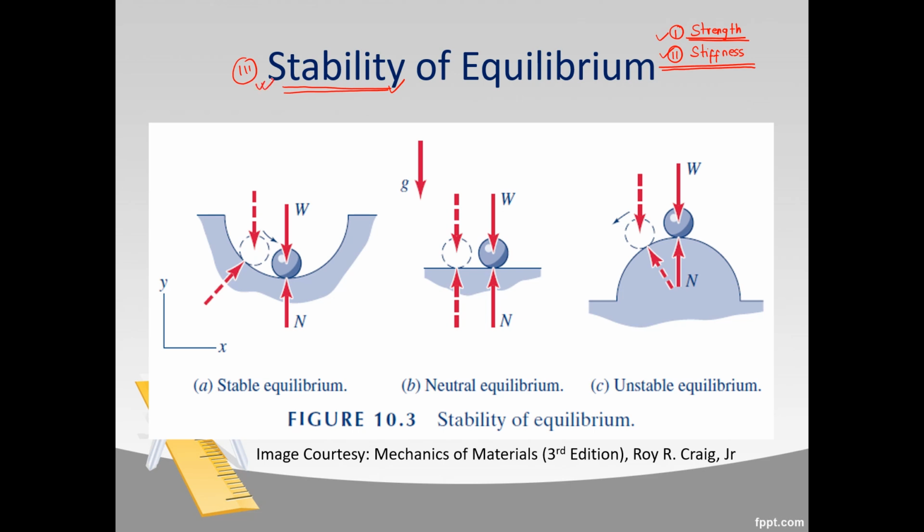That is stability. And we know this concept of equilibrium of a structure. When we solved problems relating to static equilibrium, we used this concept: the summation of forces in x direction, Fx equals 0, the summation of forces in y direction, Fy equals 0, and the summation of moments about the z-axis equals 0. Whenever we had any object in the xy plane, for it to be in equilibrium, particularly static equilibrium, these three equations had to be satisfied.